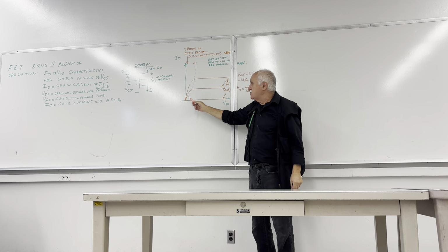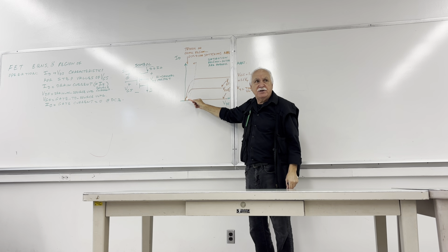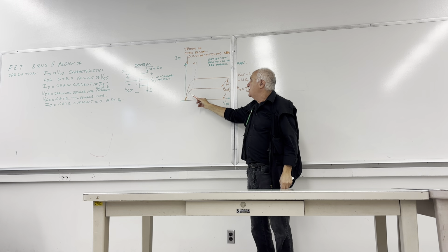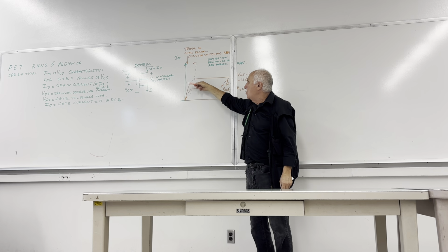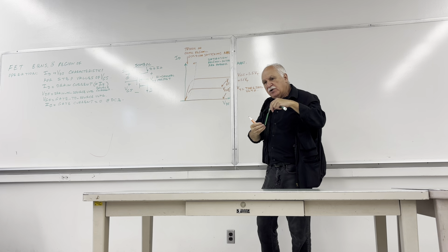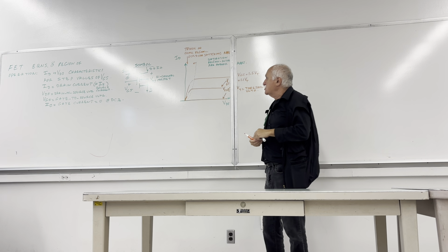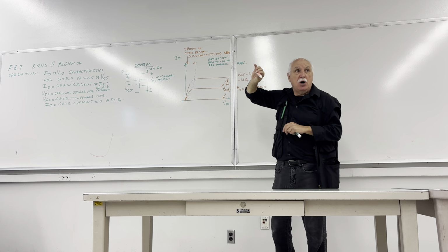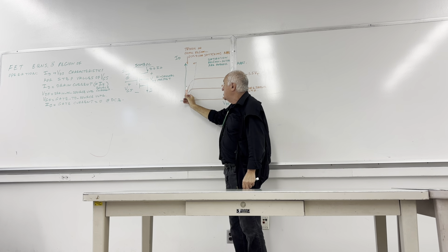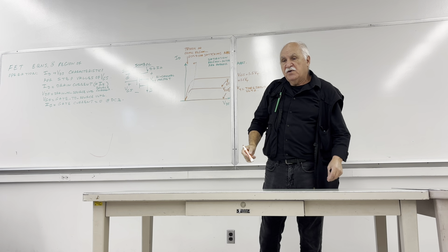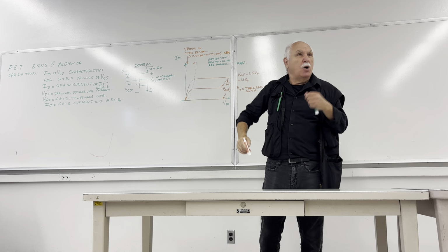Because what is resistance? Resistance is 1 over the slope of the I-V curve. The slope in here is less than the slope over there. Therefore, 1 over the smaller slope is greater than 1 over the steeper one. So it becomes a smaller and smaller resistance. Indeed, there is a VGS value called VGS on, at which the resistance at the origin becomes so small, in the order of 20 to 30 milliohm.